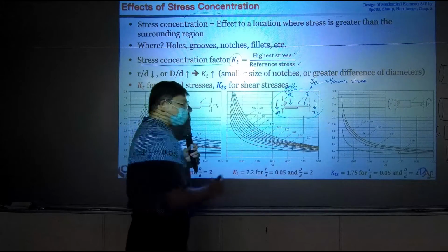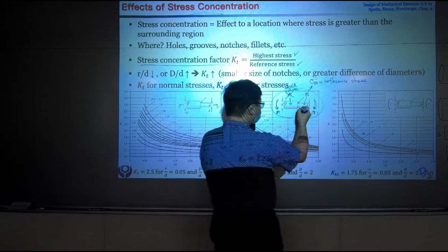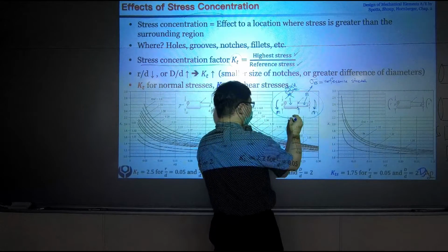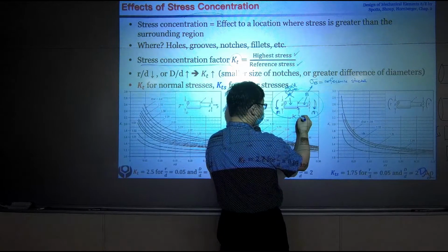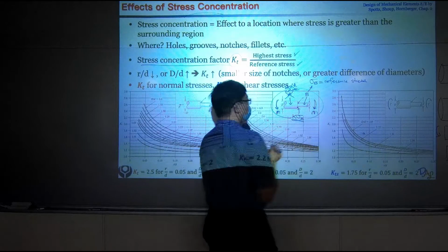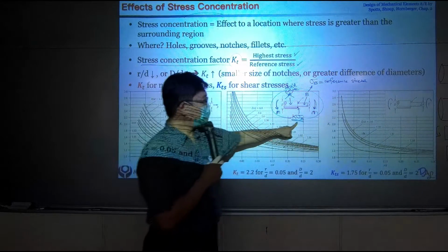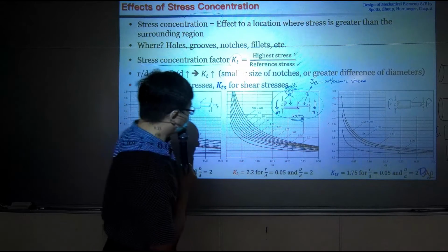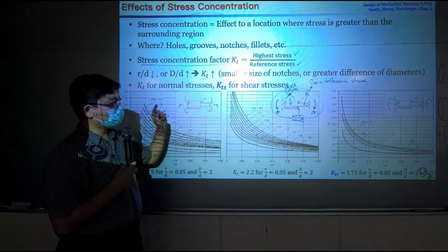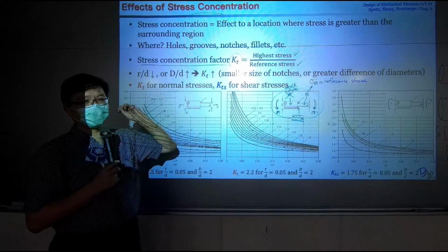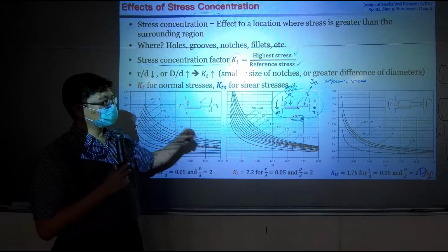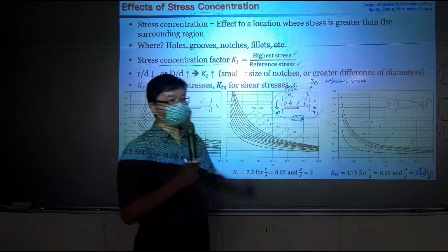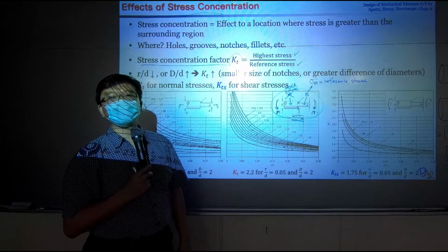So can you tell me how much concentrated stress that will be? The way this research is done is to tell you how much stress this corner will have by telling you this: K times the reference stress. So the table is telling you how many times your reference stress you will get at the corner where the stress concentrates.